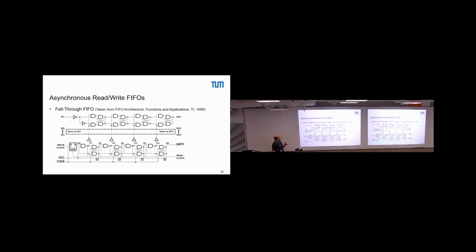So let's maybe start with what is data path, what is control path. The write belongs somehow to the control path here. So this is my control together with this full, clear, empty flags. The overall control part is this one here. That's my control path. With the lower half, I control effectively what happens in the circuit.